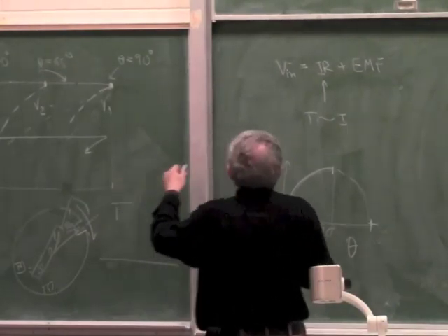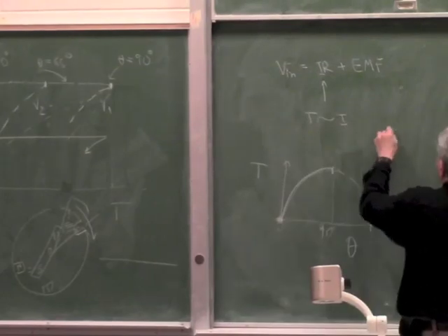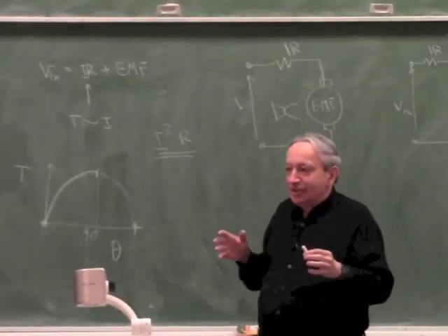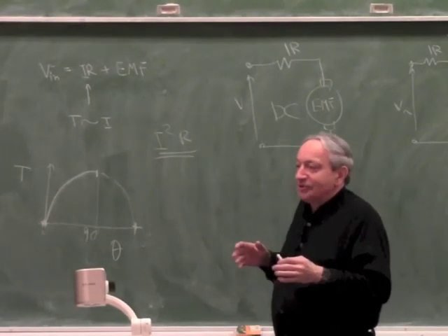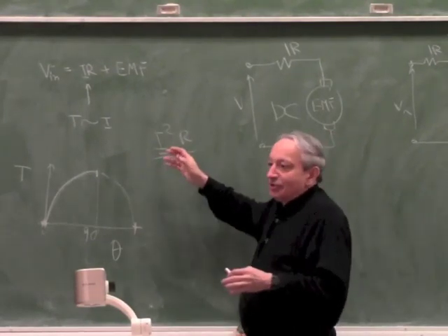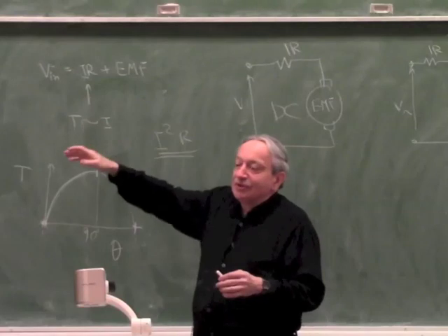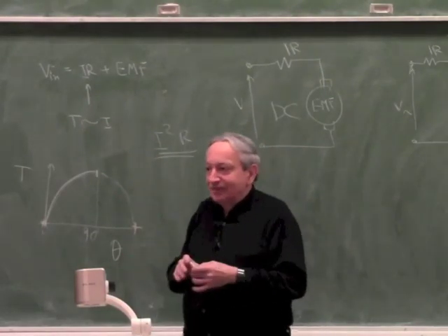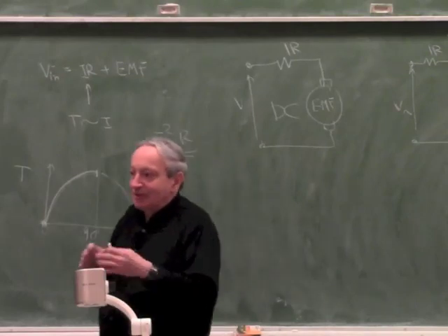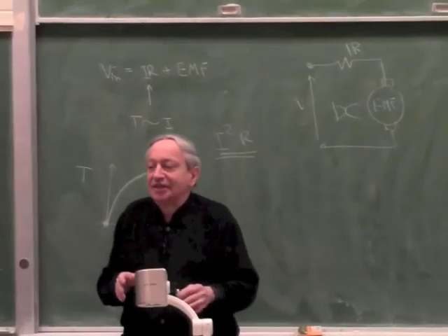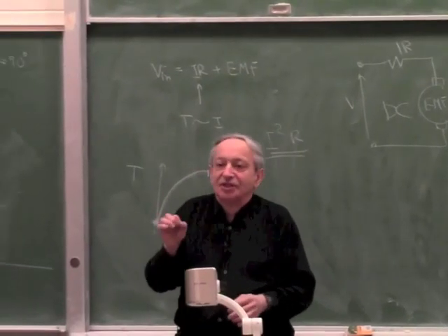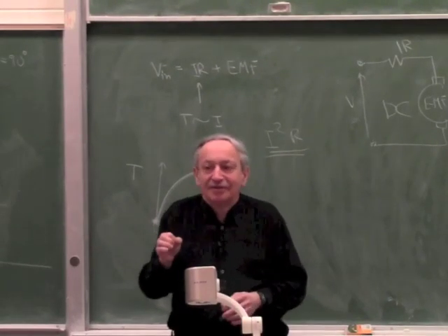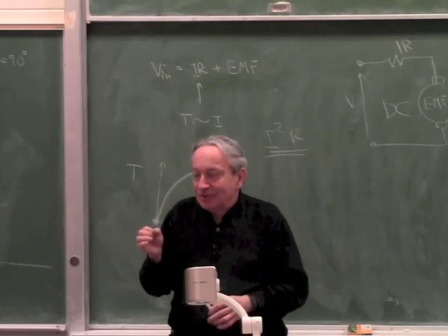So inside that motor there's a heating of I squared R, and the motor is rated for a certain heat dissipation. If the motor is rated, say, for 10 amps, whatever you play with frequency and voltage, you cannot exceed the 10 amps continuously. Maybe for a second you can, but continuously the motor has a rating. The rating has to do with the cross section of the copper winding. So the motors are rated by current, not by voltage basically.